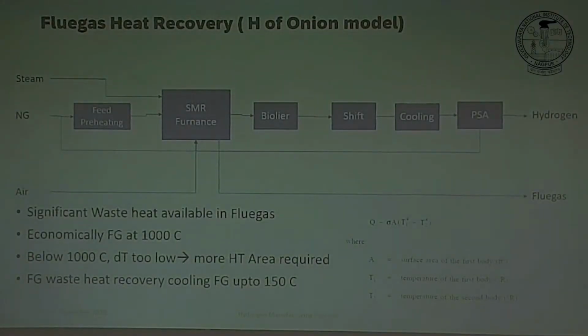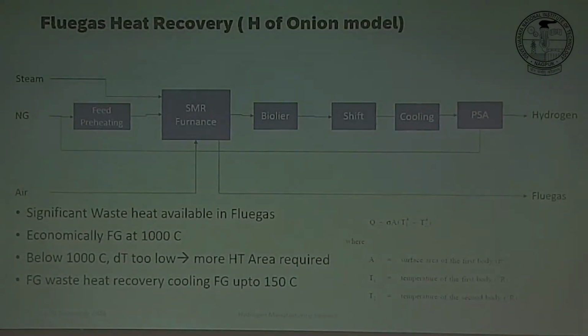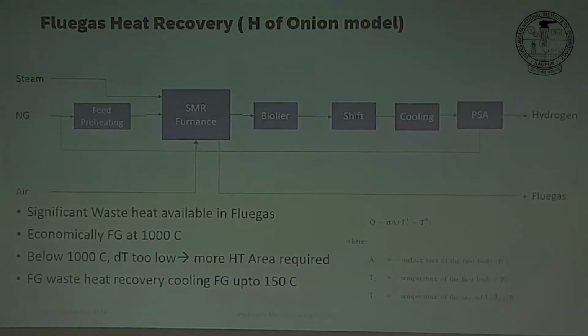This is called tail gas. So during the desorption step, we supply hydrogen. First of all, it's depressurized, right? You don't supply any sweep gas. So the gases are desorbed automatically, and all these components end up here. All are in this stream, right?